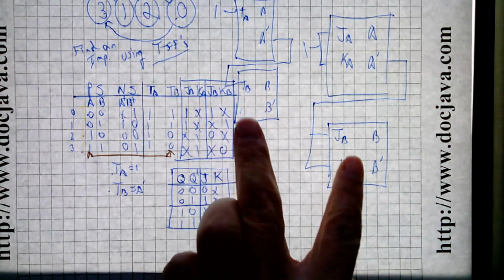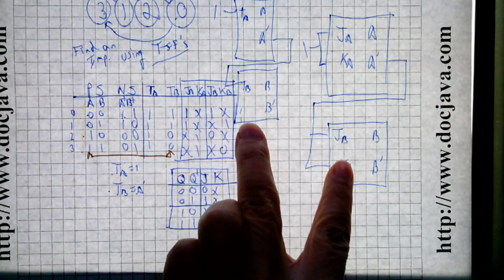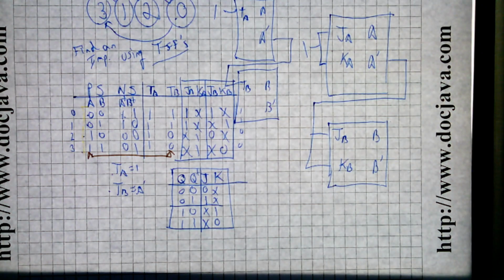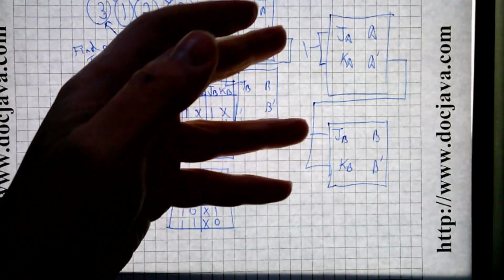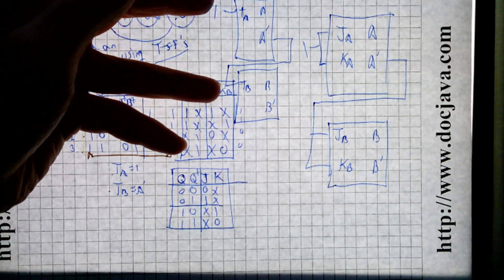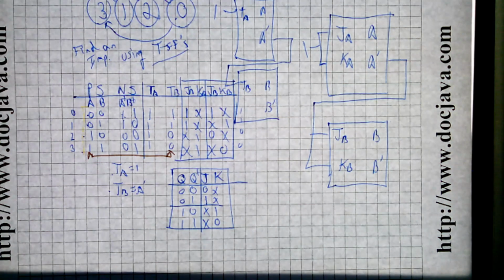So in fact, toggle flip-flops can be created from JK flip-flops just by wiring J and K together. That's pretty cool, isn't it? So by direct analogy, you were able to obtain an implementation that was identical in complexity to the toggle flip-flop in this particular case. That won't always be true, but there it is.